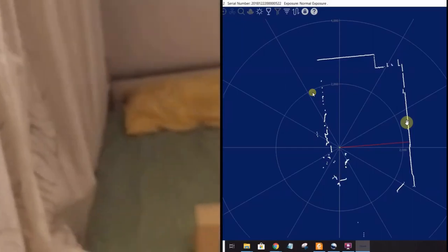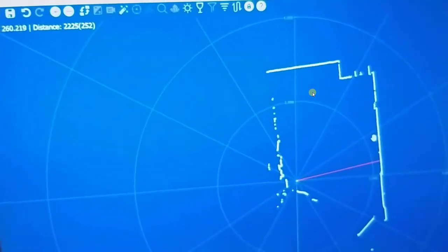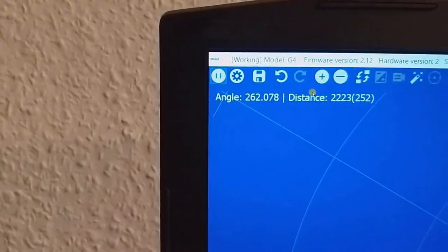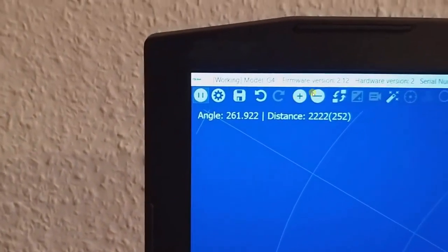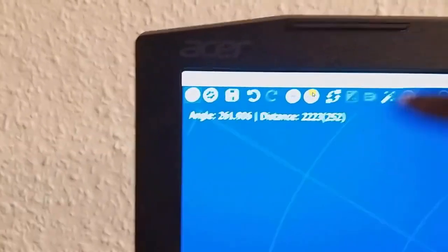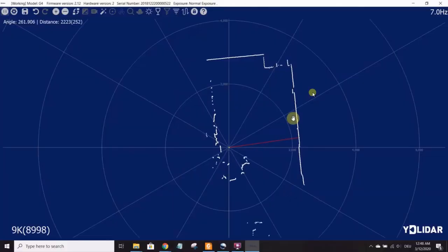So let's verify 2.22 by using the other ranging device. We align the center of the LiDAR with the end of the other ranging device, and point the laser beam at the wall, and lock in. Let's see the result. That's 2.24 meters. So this is within, I think, reasonable bounds, considering that I'm moving my hands and all that, but it still matches reasonably with the 2.22 meters.